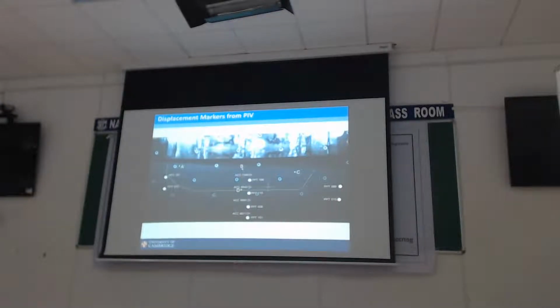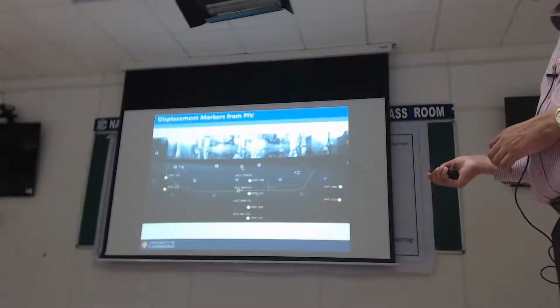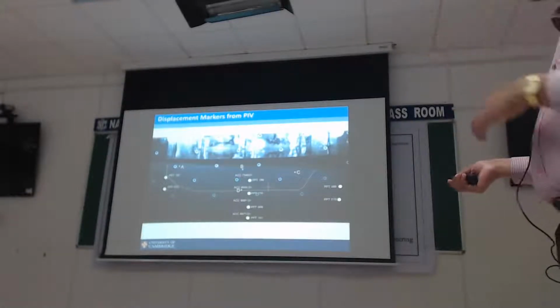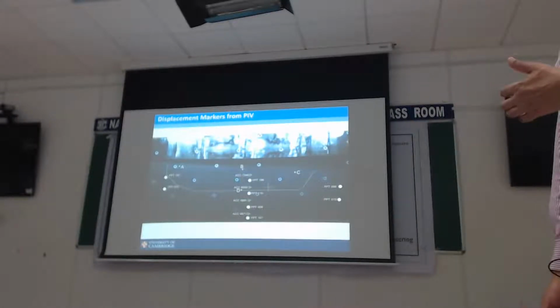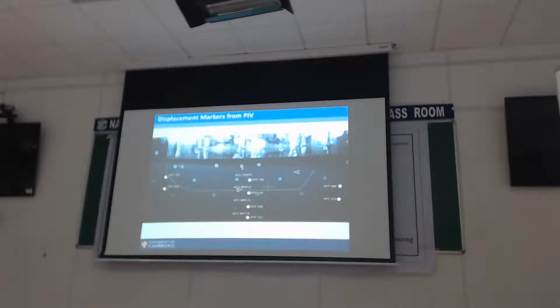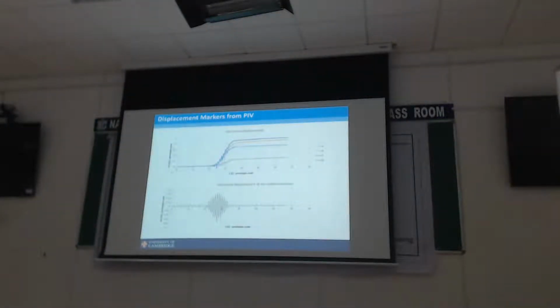Also, what PIV allows you to do is to pick certain points. So I picked A, B, C along the slope and D at some depth. So for those particular ones, I can get the time traces. You don't need LVDTs to measure displacement. You basically follow where these points are moving throughout your earthquake, which gives me displacements. So I can use just that information I showed you earlier as a time trace and see A, horizontal displacements, A moved least, B moved most, and others fall in between for those 4 locations I have shown.